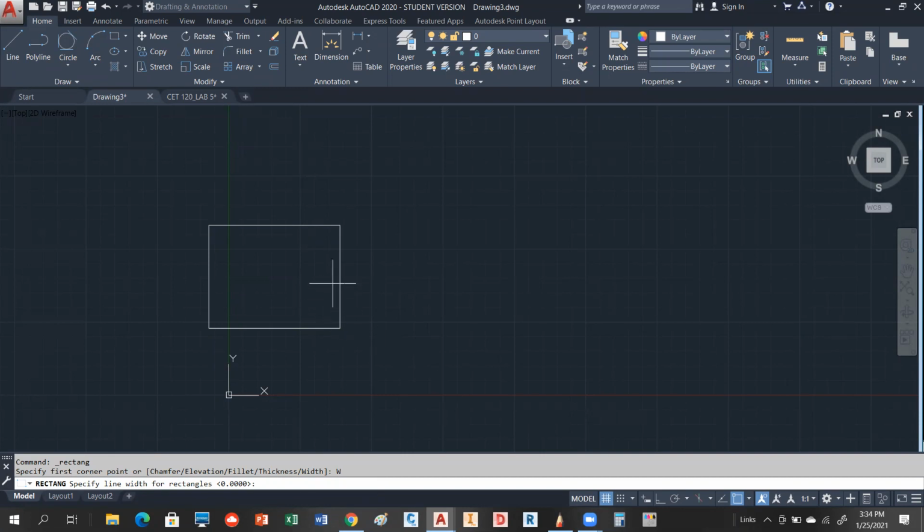So when it comes out, if you tell it the width is, let's say, 0.2, it'll be 0.1 in this direction and 0.1 in this direction. So the actual points that you select are going to be embedded inside of it. So don't make this too big. If you're following with me, I'm going to make this maybe 0.25. Okay, 0.25.